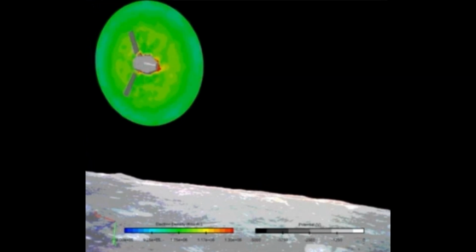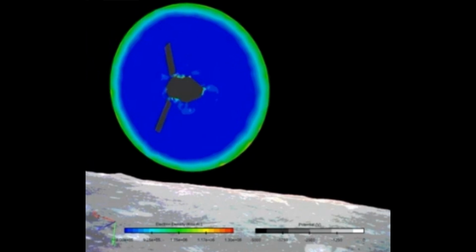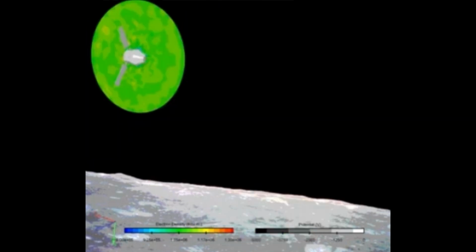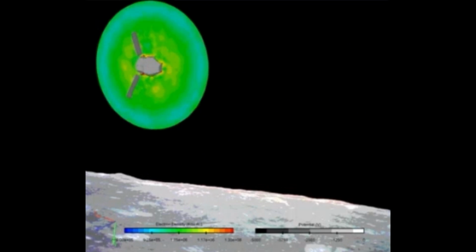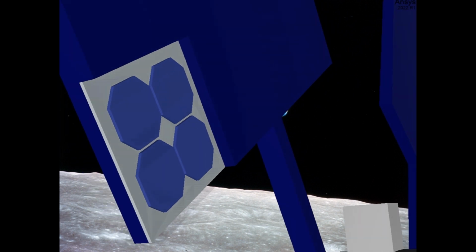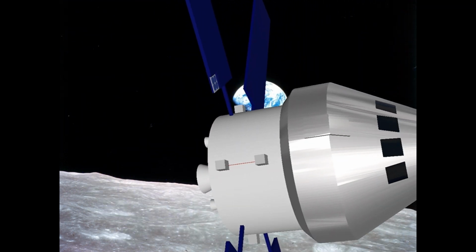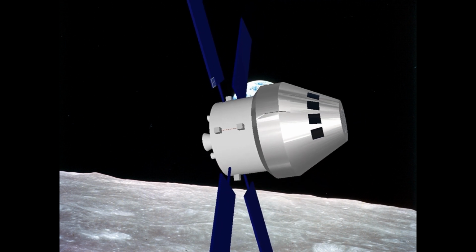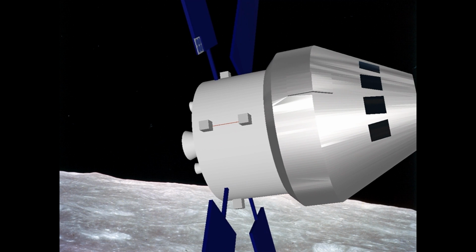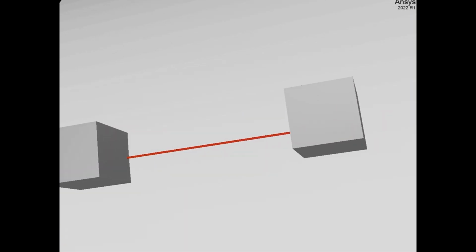However, a lot of the radiation that is present in orbit is energetic enough to penetrate through a lot of shielding and create problems at the component level on the PCB. One of the methods to mitigate this issue is by adding extra shielding at the component level, maybe a couple millimeters of aluminum in one place or another, or even changing the enclosure materials or the enclosure thickness in which